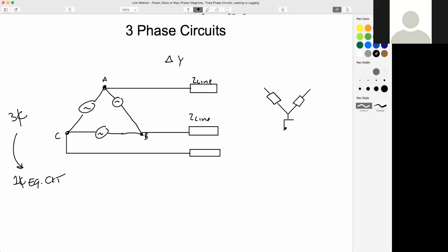I'm going to go ahead and plug in some values. Actually, you know what? Let's draw this upside down. So who can tell me what's the easiest 3-phase system to work out on paper? Is it delta delta? Is it delta Y? Is it YY? Is it Y delta? What's the easiest? YY, exactly. Perfect. Okay, good. So anytime we're dealing with anything other than a YY system, we want to make it a YY system, right? And who can tell me why? Why is a YY system easy to work with? Why is that the goal?